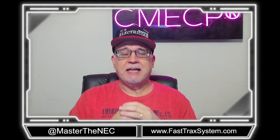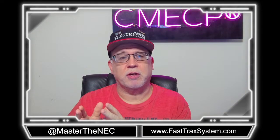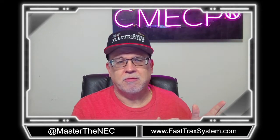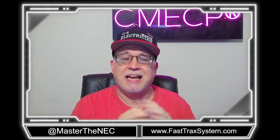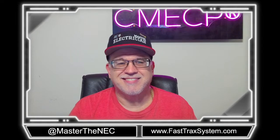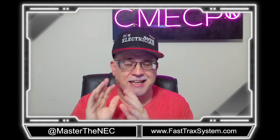Moral of the story, think about the generators you purchase and the application that you're using them for. If you are truly going to use it just for portable needs, right, then do me a favor. If that's the application you're going to be using it for, get a generator that has a bonded neutral and use it for those portable applications. All right? Okay, folks. We'll go in depth in other applications from generators, interlocks, and all this kind of stuff, and the feasibility of those in a later episode.